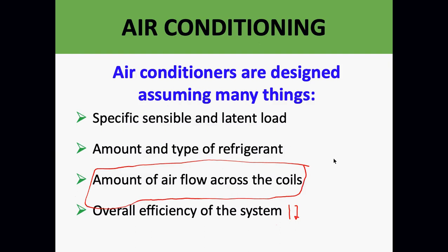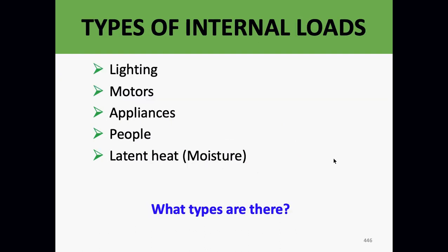Blockage. People plant trees around the condensers to hide them from the street. Those trees and bushes can get too close and can really affect how well a system is working, and it will affect how well they're cooling the buildings.